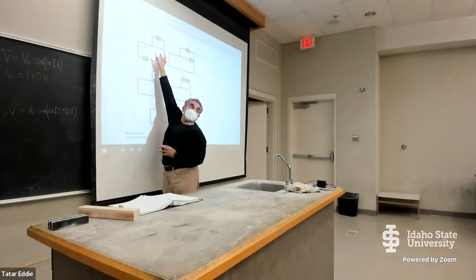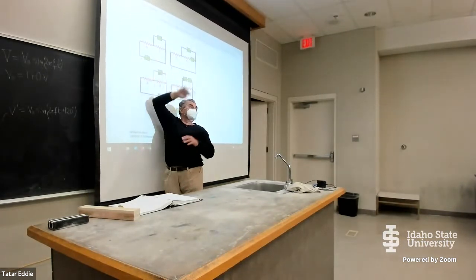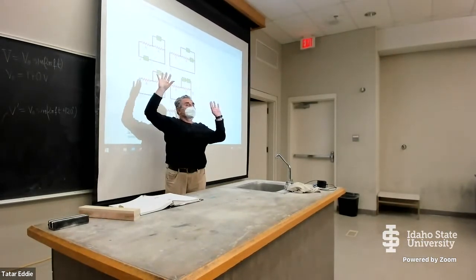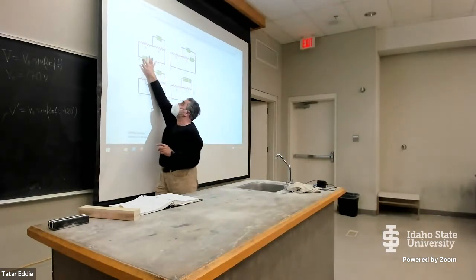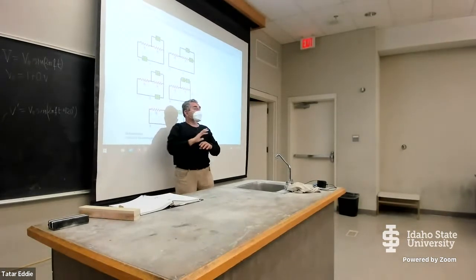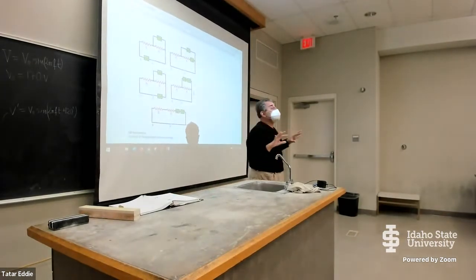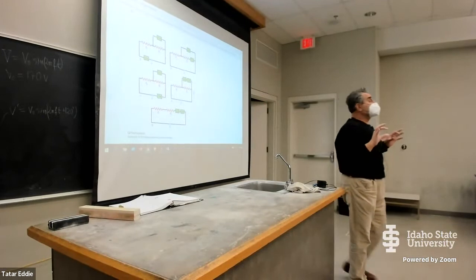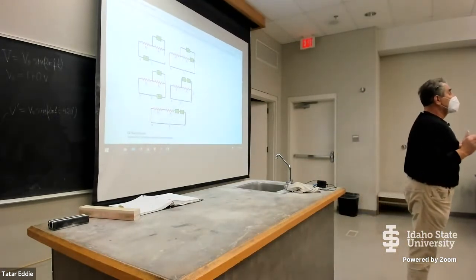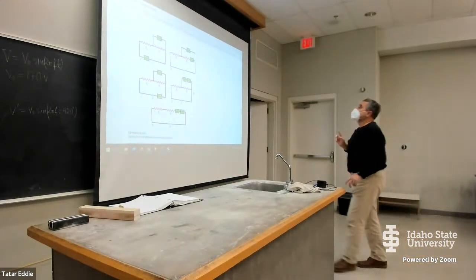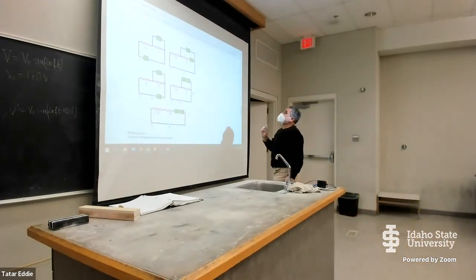Remember, no current is going to go through the voltmeter because the voltmeter has infinitely high resistance. So look, it is a closed circuit and the same current has to flow through every single device connected in series. If B had the VM and AM switched, would it be accurate or no?